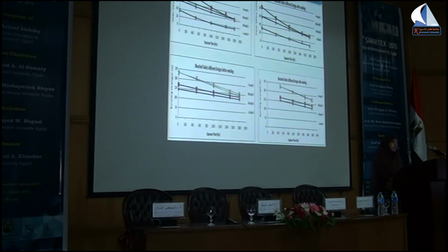The fabric, in the same manner as in the previous figures, with increasing exposure time, the color value and bursting strength decrease. But in color value, we can notice that after washing the color value decreases compared to before washing because of the chemical detergent in the washing process. But in bursting strength, we can notice that the bursting strength after washing increases because of the fabric shrinkage.